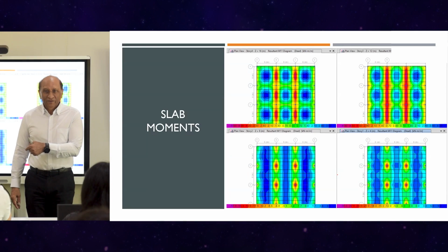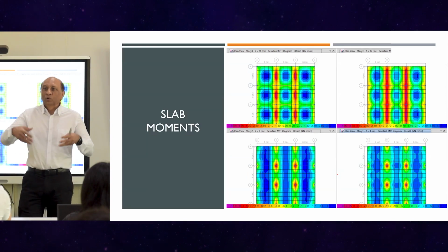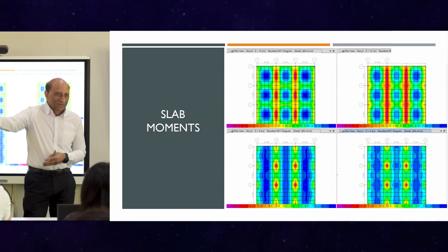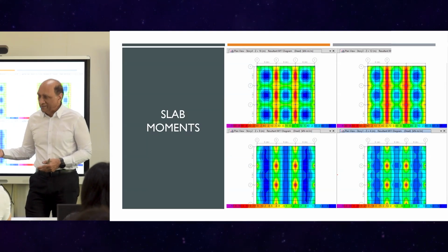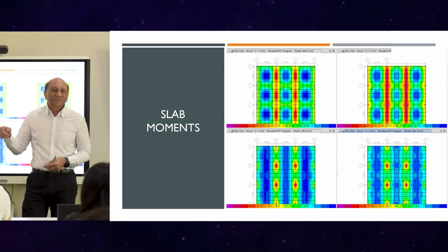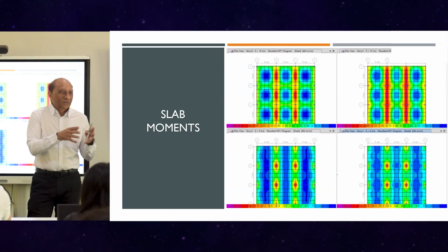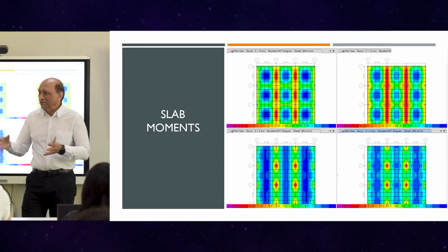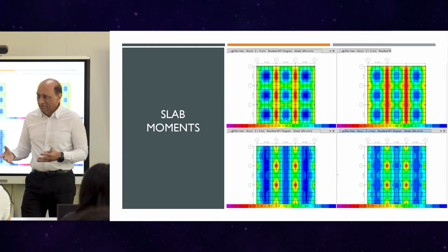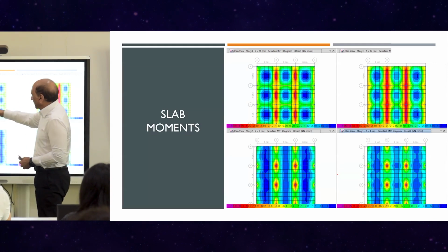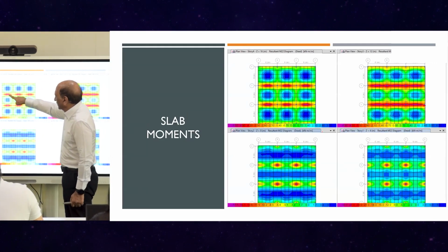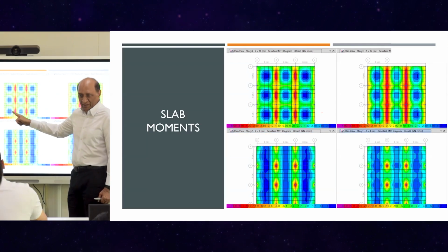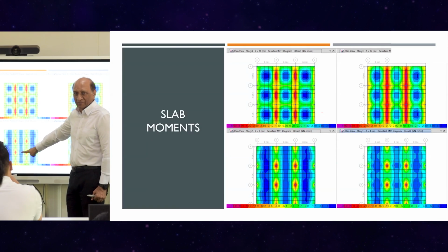And I said, you are doing the same thing. You just don't know it because you are transferring all the load once to the beam, and then you're designing the beams to carry all that load again to the column. So you're also carrying the load twice before it reaches the column, but you just don't see it that way, because once you think I'm doing the slab, once you think I'm doing the beam. But in reality, both of them are working as a system. So here, that is correct. The load is being transferred here and there, and here and there. It's a two-step transfer. Here's a single-step transfer in both directions.